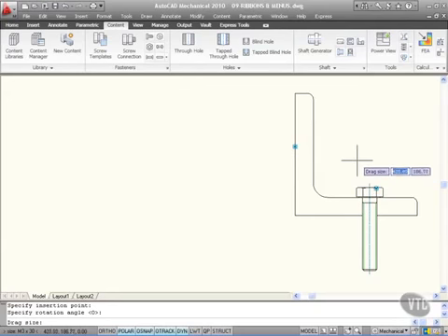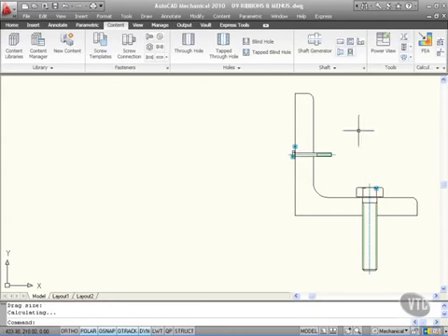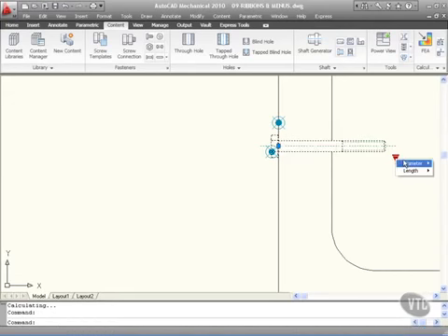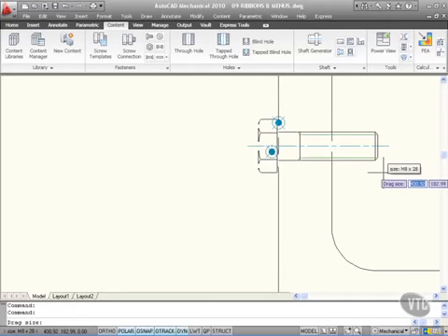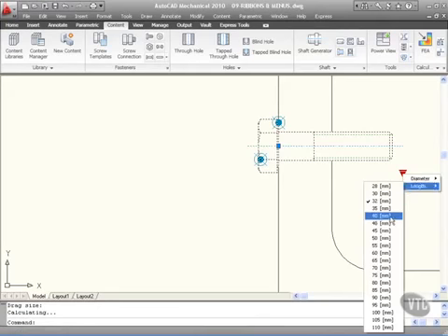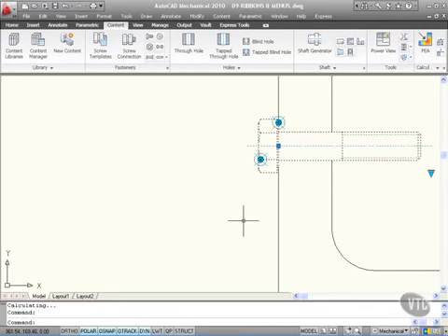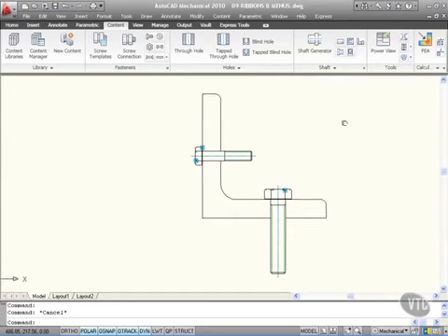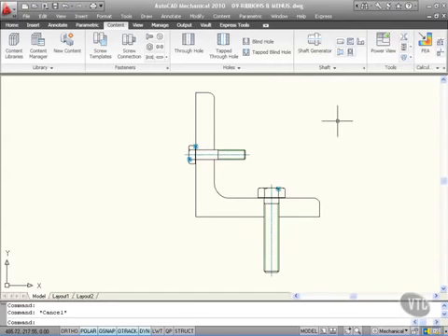And I'll go for just a size there. As you can see, I can only go so far, because that particular family of bolts only go to a certain length. As soon as I click that, though, it's inserted again. And again, notice it's a dynamic block again. So I can click on it. I can click there. I can increase the diameter to, say, an M8, like so. Drag the size like that. Click there again, go for length, and I'll go for a standard length of 40. And there we go. Hit escape to deselect. And I've done all of that off of the ribbon instead of using the content libraries. So you can see that there's lots of different ways and means of getting around here.